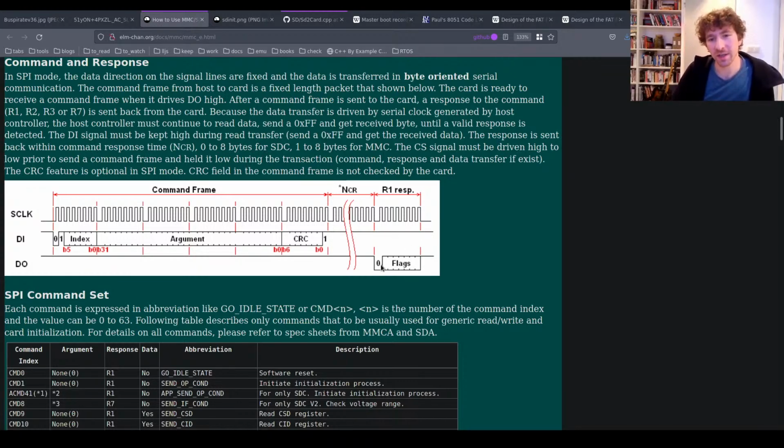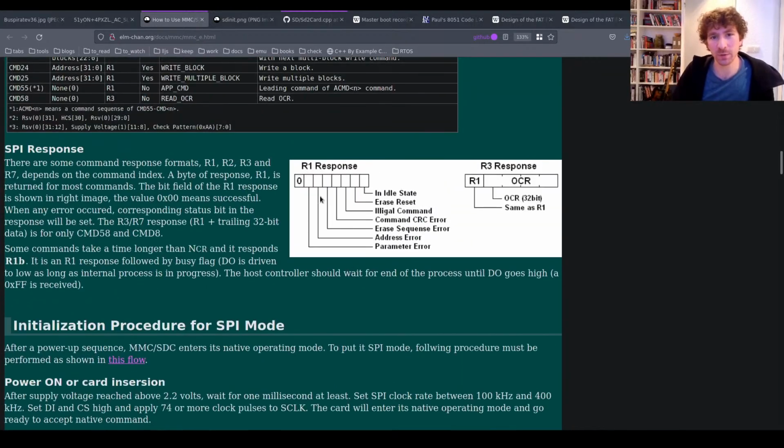And the nice thing is, and they've designed it this way obviously, that the response byte has only 7 bits, and that is not an accident. It's not like we only had 7 pieces of information to transmit here. They purposefully chose 7 so that this topmost bit could be a 0, which would mean that you would never ever be in a situation where your response was FF. And I think that's really beautiful. That's the kind of thing you see when you dive into these protocols and you look for the little gems in these things. That's one of those little gems, I think.